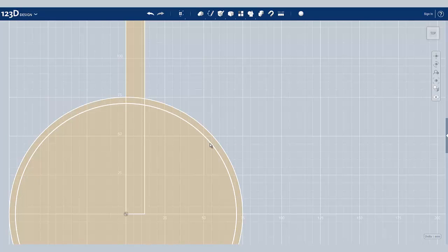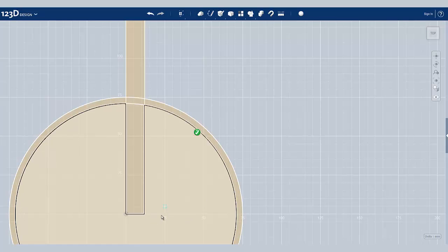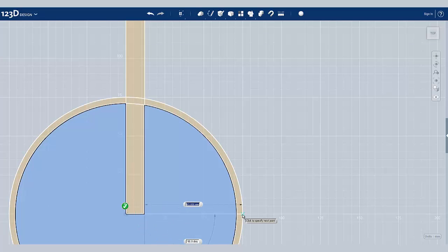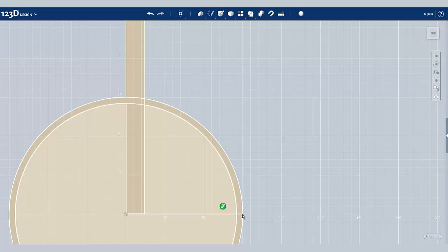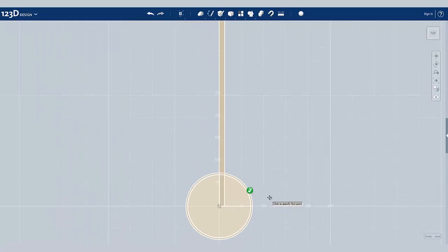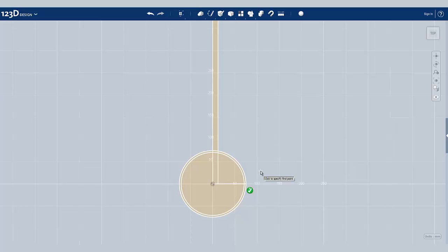If we revolved the area between our two circles right now, we would make a whole sphere. In order to get a hemisphere, we will have to chop off some geometry. To start though, I will create the line that we will revolve our shield about. We will use the polyline tool from the sketch tab. We'll start off just by creating the line from the bottom of our rectangle to the outside of our circles. I hope by now you can see how, by revolving these shapes about this line, we'll get our Viking round shield.